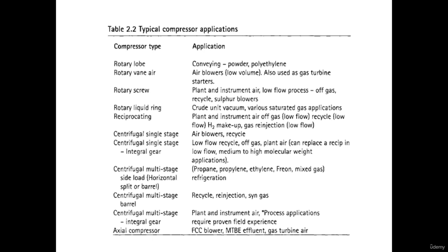Centrifugal single stage integral gear, for low flow recycle of off gases. Off gases, instead of flaring, or directing these gases to the flare, you use these gases in separators or the like to compress them and use them as a fuel or in many applications. So it's used for low flow, medium to high molecular weight applications.